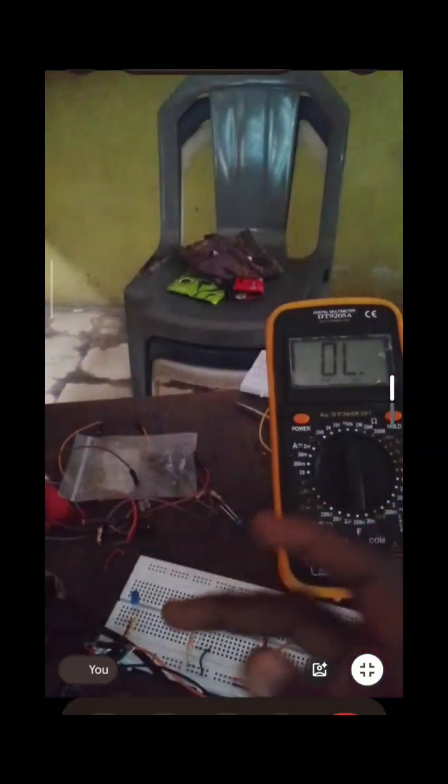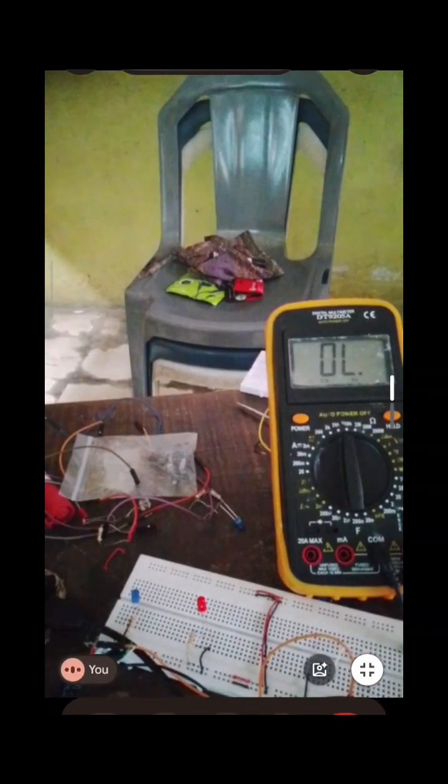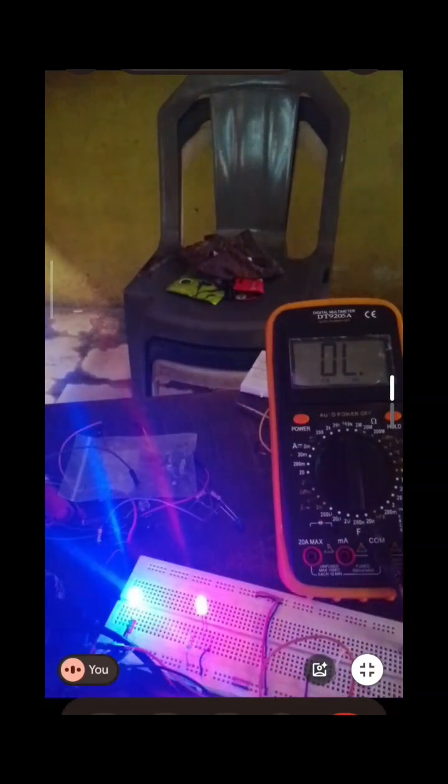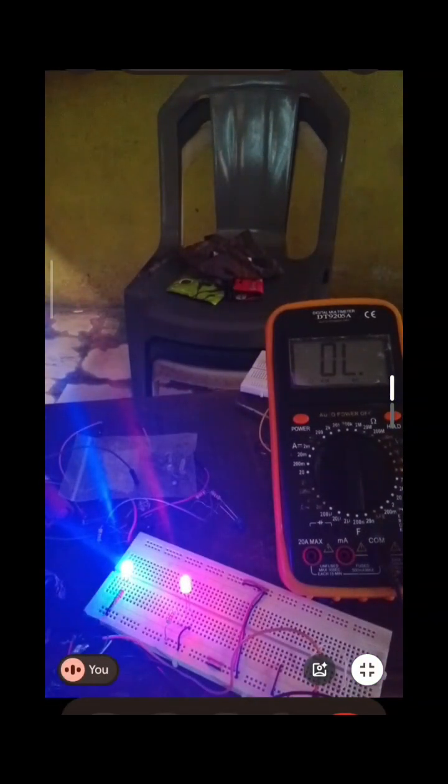And a little recap. We talked about resistors, talked about LEDs, that they are a diode also, and a diode allows current flow in one direction. And as I did earlier, I swapped the way I connected the LED. I also said that blue light consumes more voltage, as I did with my multimeter. And I also did a demonstration of a resistor in series and a resistor in parallel, and also explained how this breadboard works. So that was all for today, and the next class is going to be even greater than this.